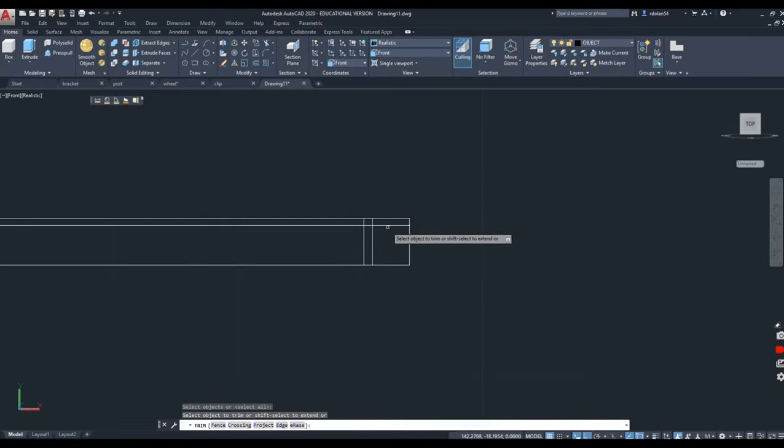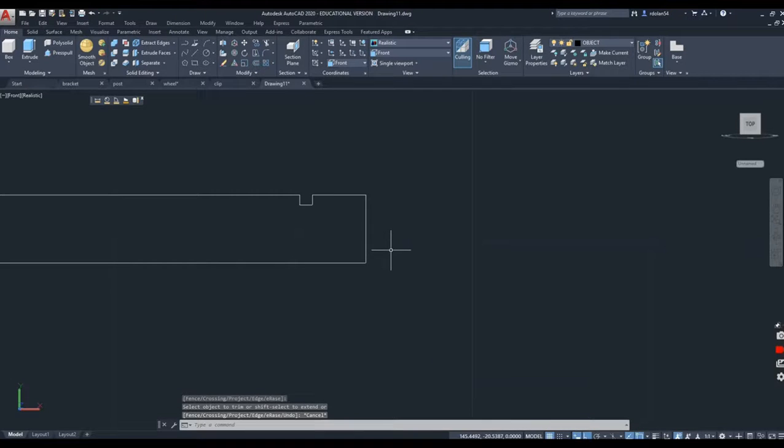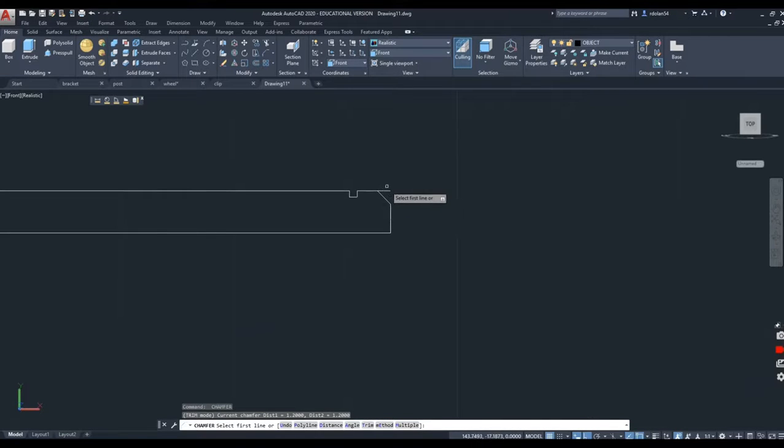Then I'll trim these guys off. Here, here, here. Oops. And there. Okay. Trim this guy off here. And now I'll put my chamfer on there. And the chamfer is distance of 1.2, 2 times. I'll go here. Okay, I think I got an extra line there.